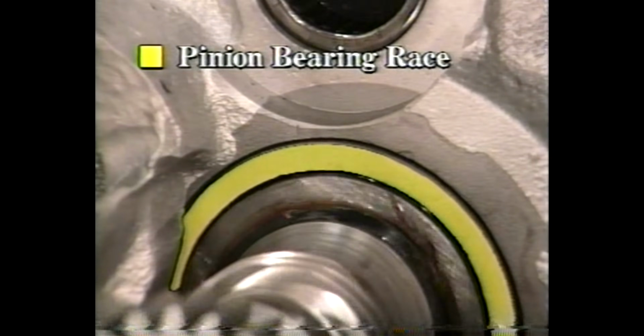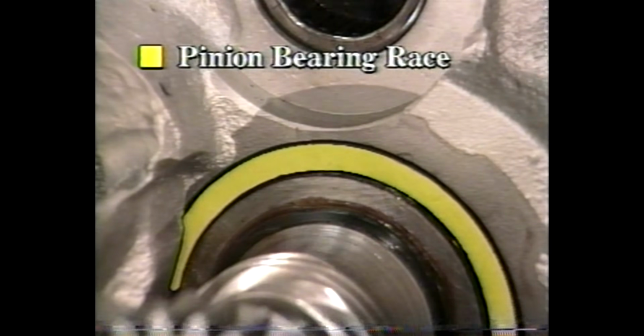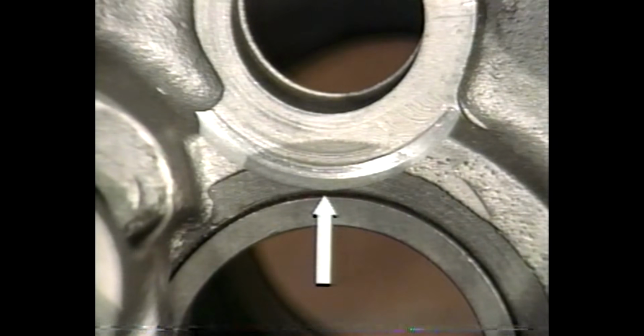Be sure that this change, which is required to give necessary clearance for the cam lobe, stops before it cuts into and weakens the pinion race itself. The resulting clearance between the rear intake cam lobe and the pinion shaft bearing race housing should be at least 0.010 of an inch.